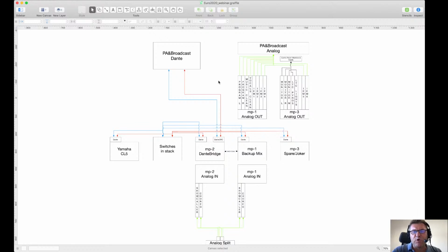I guess at that point it's quite clear we had to provide a bunch of channels down to the field of play. The main bidirectional connection was a Dante SRC back and forth between the field of play and the control room, backed up with analog feeds for the PA and broadcast, and fixed analog with no backup in this case, because we were in exactly the same physical room. So we had a physical connection of the local analog output towards the active speakers for the monitoring: left and right for the sound engineer, monitor for the choreographer and the show caller, and LTC, separate LTC, with identical feeds for pyros and lighting consoles.